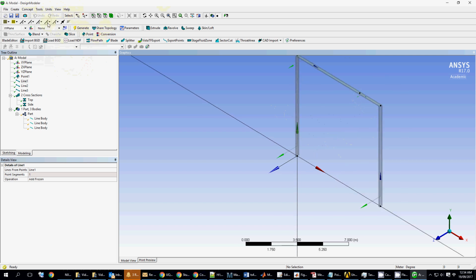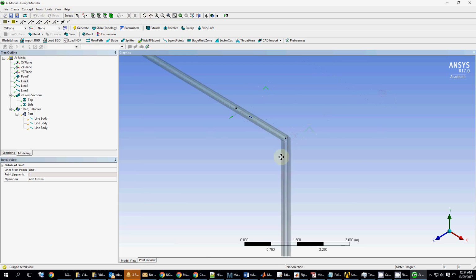What you see from here is your beam is lying down, which is not right. We want it to sit straight up. So what we can do is, again, in here there's an option of selection tools. This is if you want to select nodes. This is if you want to select an edge or a line.